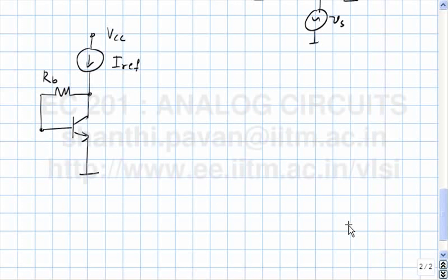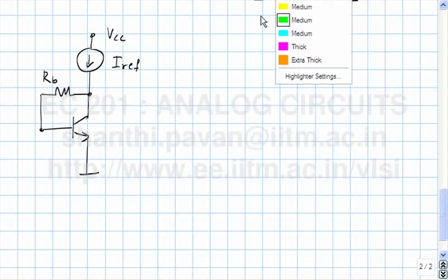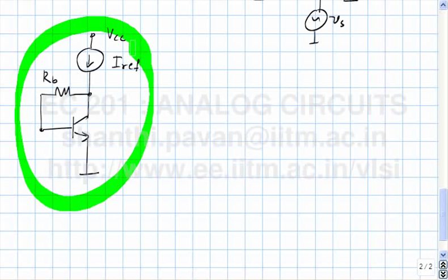One is, of course, that once you have bipolar transistors, base current will flow. The actual collector current will be slightly smaller than IREF by the base current. Since the base current is very small, typically about 1% of the collector current, perhaps it's not a big deal. Do you see a fundamental problem with this arrangement? Think about swings.